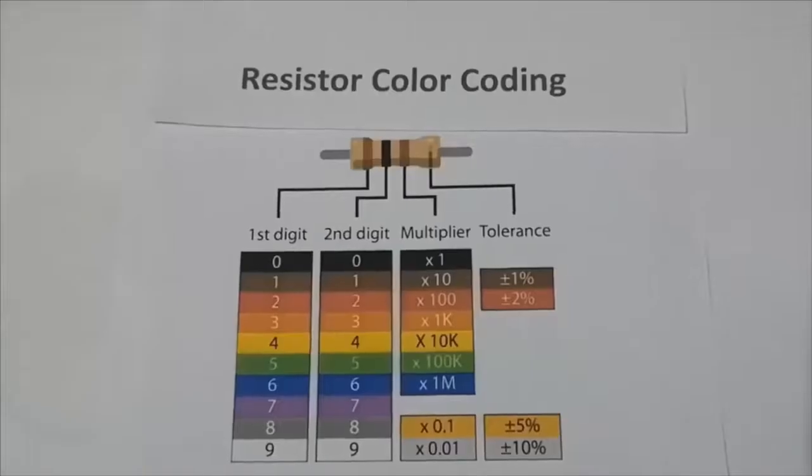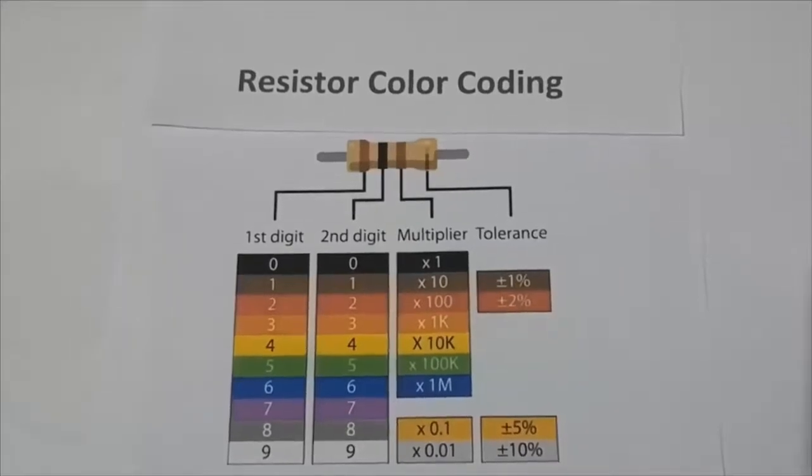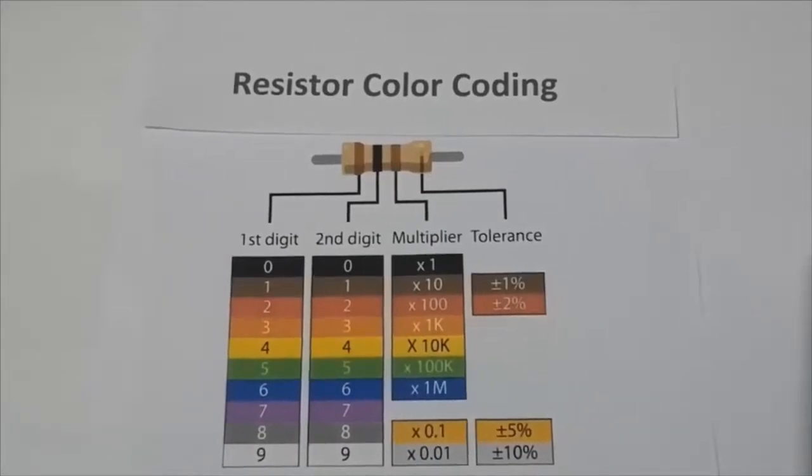Today I will discuss the resistor color coding. Resistor color coding is a coding system that uses color bands to easily identify the resistive value and percentage tolerance of the carbon resistor. In carbon film resistors, there are two color coding bands, the 4 bands and the 5 bands. Before we start the conversion, let us first determine the different equivalent numerical values of the different color codes.